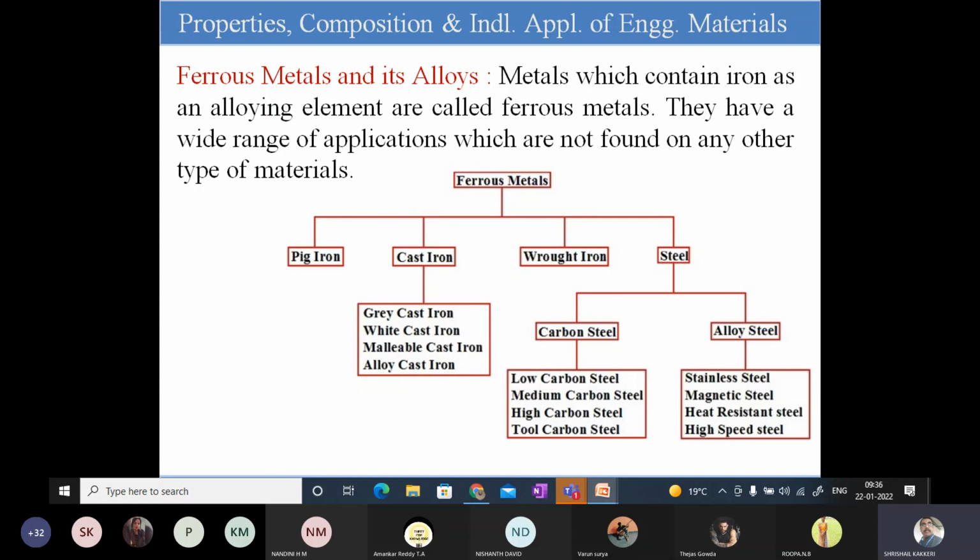Okay, how can we find it out? The cast iron, just by naked eye, we cannot find out what this cast iron is. By looking at its properties, we can say this is cast iron, this is wrought iron, or this is steel. If we throw it or give an impact load onto the cast iron, it will break, it will not bend. That is one of its natures. Plastic will break, it will not bend.